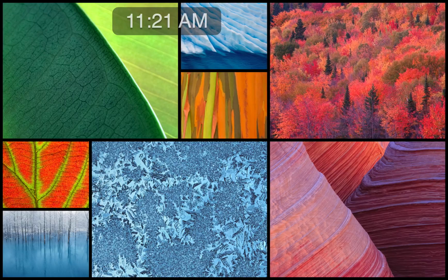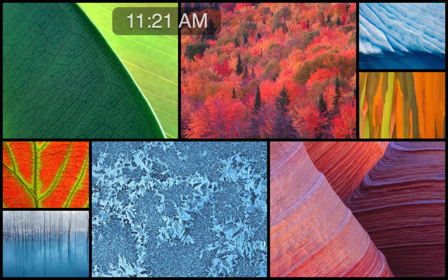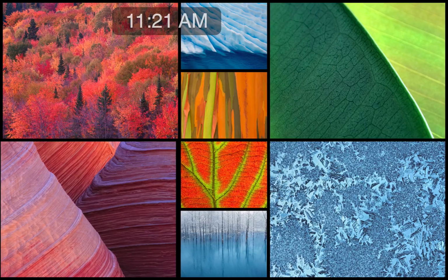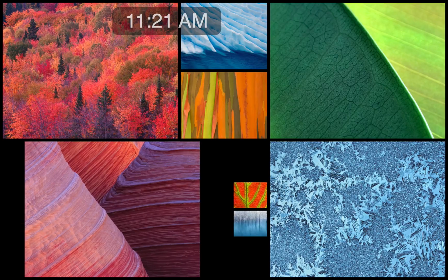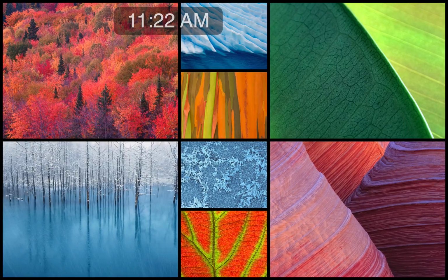Okay, so let's do the same thing over here. So one thing you got to be really careful about is you can easily mess your model up by moving stuff, which I just did. You probably didn't even catch it. I just moved the floor. So take your stuff that you care about and pin it, okay? My floor is now pinned. All right, now I'm gonna do these studs.